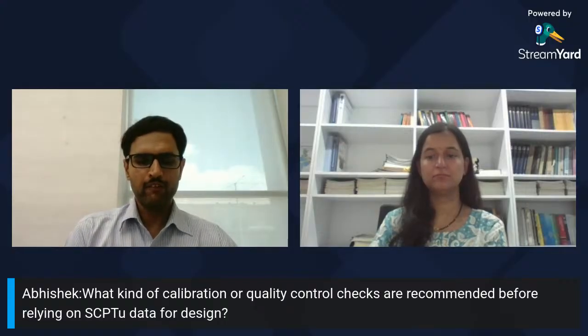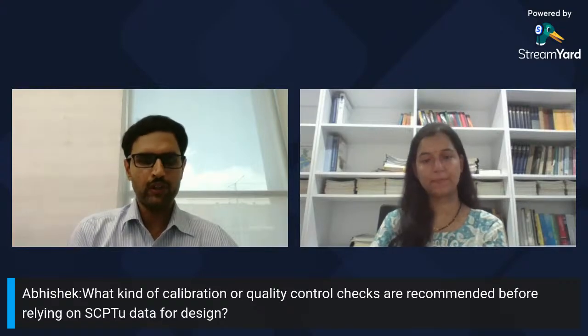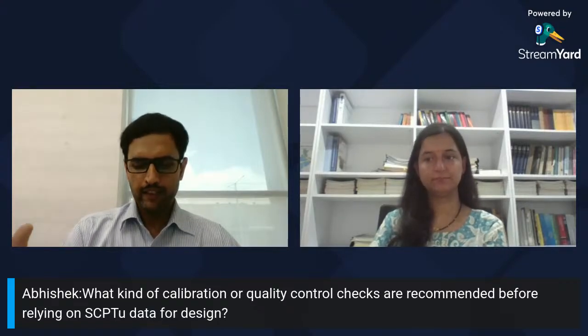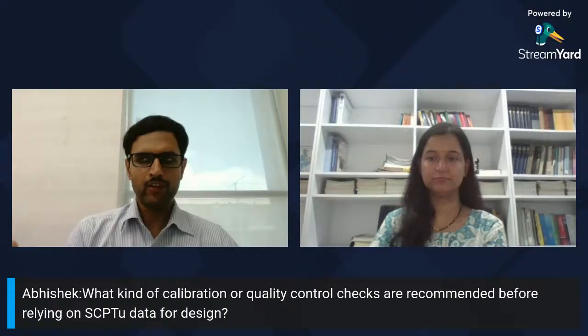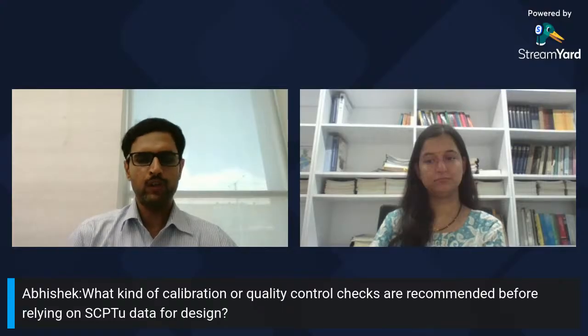And your main shear wave should have a consistent delay between the top geophone and the bottom geophone. So by inspection of these seismograms, it can tell you whether the data is of a good quality or not. And then when you collect multiple seismic measurements at the same depth, you can calculate the coefficient of variation to check whether your data is repeatable at that depth or not. So these are the ways you can ensure the quality of your data.